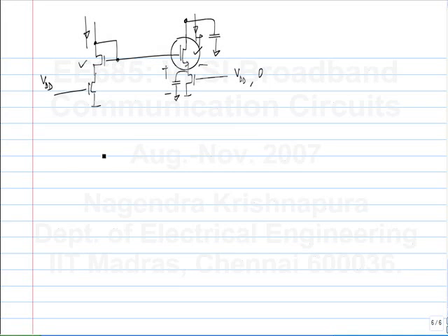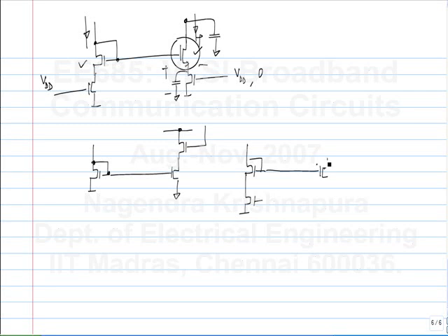So in one case you have this. And the gate source voltage here depends on what the current source is connected to. So this can be high, so you can have a large drop across this. Whereas in the other case, what is the gate source voltage of the switch? The gate source voltage of the switch is VDD. So the resistance will be smaller, or equivalently you may use a smaller switch here, whereas you need to use a larger switch. Okay. So in general, switching at the source is better.